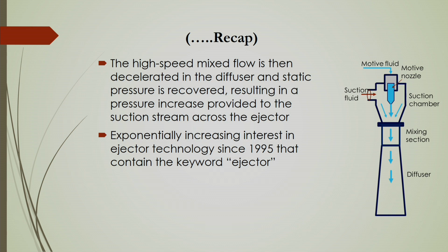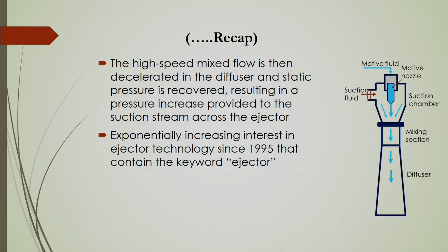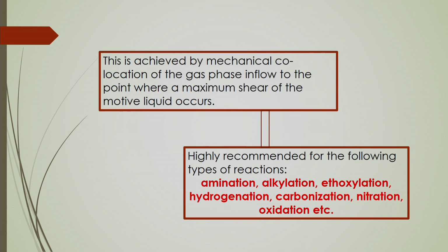And also this high speed mixed flow is then decelerated in the diffuser, and static pressure is recovered, which results in a pressure increase of the suction stream across the ejector. Interest in ejector technology for the intensification of chemical engineering processes has been increasing exponentially, since 1995, with ejector systems and their applications as a keyword. So, this is basically achieved by the mechanical co-location of the gas phase inflow